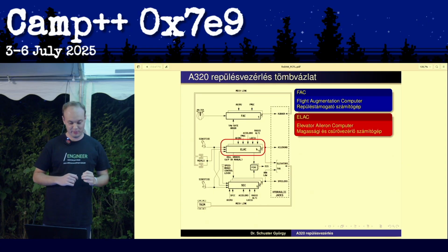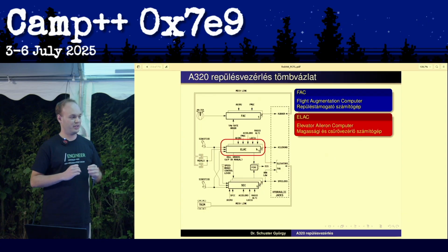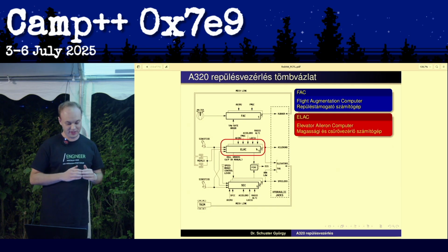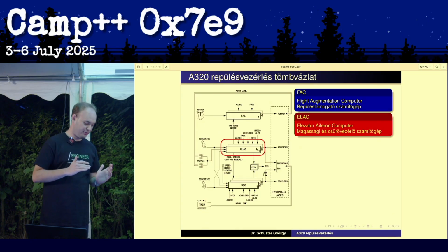Basically you have to implement something called a voting logic that compares the two outputs, or it can be something as simple as, in a simpler system with two microcontrollers, placing a logic gate on the two outputs to combine them, but that can also fail on its own.